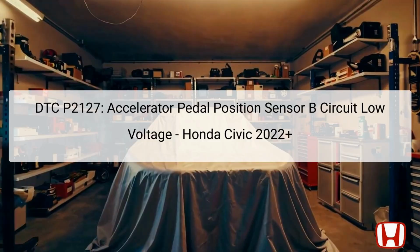DTC P2127 indicates a malfunction in the accelerator pedal position, APP sensor, B circuit, specifically indicating that the output voltage falls below a certain threshold. In Honda vehicles, particularly the 2022 Civic, the APP sensor plays a critical role in determining the position of the accelerator pedal, which directly influences the throttle response.